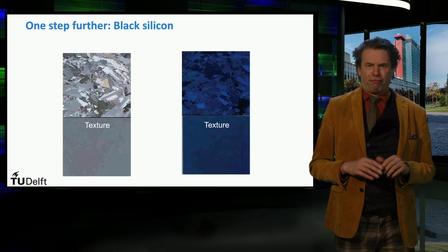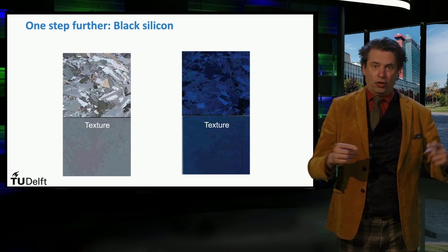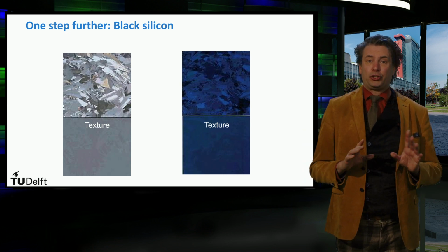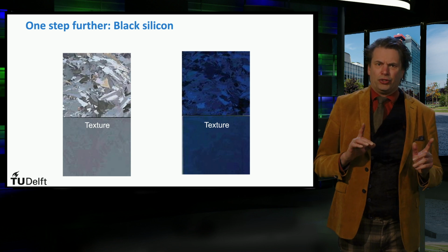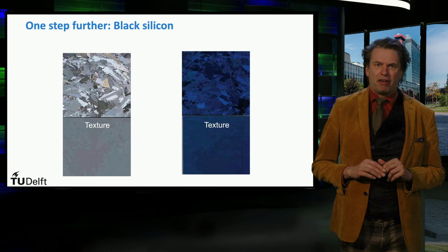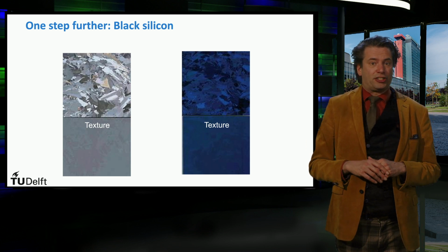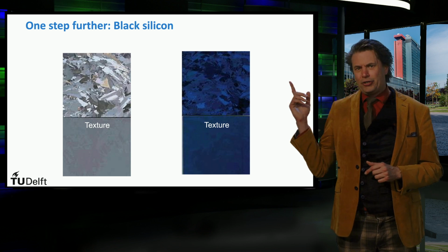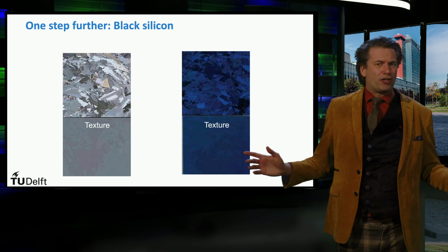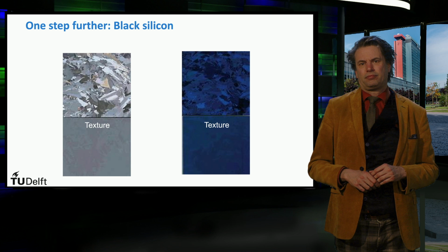Here we see a flat multicrystalline silicon wafer with and without the silicon nitride. Under these wafers we see two wafers with and without silicon nitride layers as well. The only difference is that the two wafers at the bottom have textured surfaces. The wafers are placed in the same illumination conditions as the flat wafers. By eye, you can already see that these surfaces are darker and therefore reflect less light.